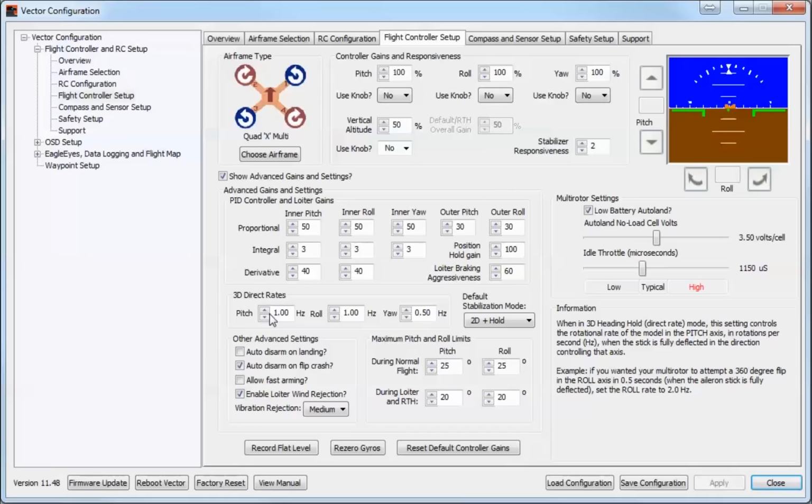One thing that I did get answered, because I asked the question of John, is that this also affects center stick mode. I found that the rolling in center stick mode was quite slow. There was quite a large radius of the roll, and from my point of view, I would prefer my multi-rotor to really flip around quickly, because usually you lose a little bit less altitude, and also it's easier to get control of it if it does flip quite quickly.